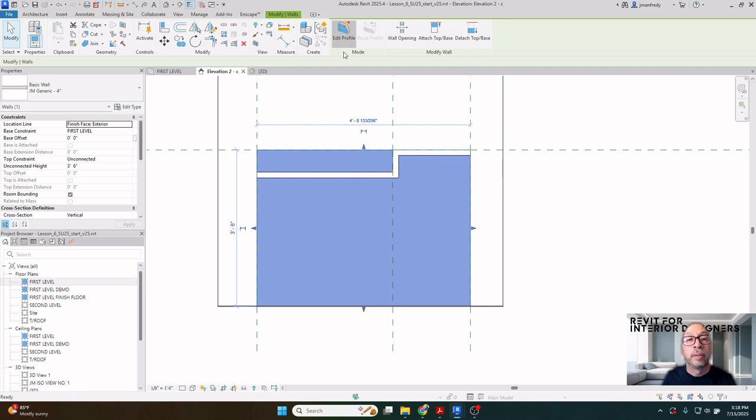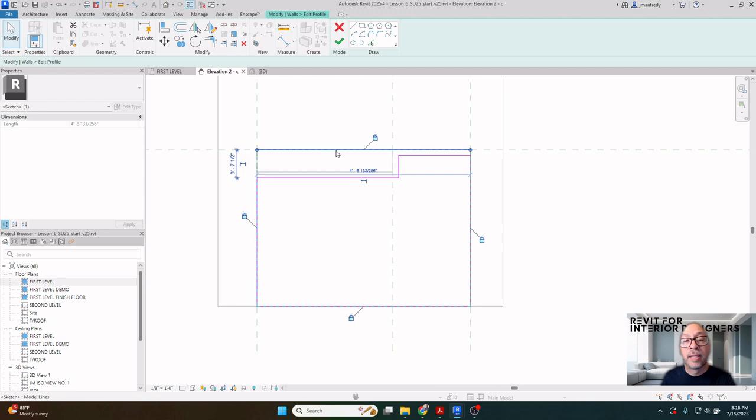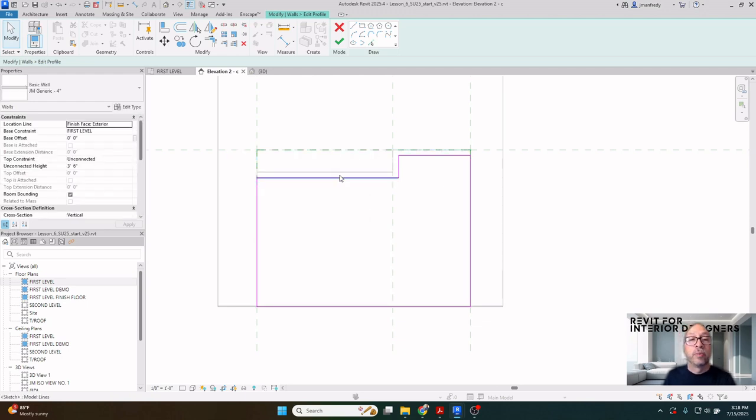I'll use the Pick Line command, and I'll pick the edges here and here, and the bottom of this. Escape, Trim, TR, and draw this without that line there. Delete on your keyboard. There's the wall that traces the edge of that countertop, 4 inches thick. Hit Apply.